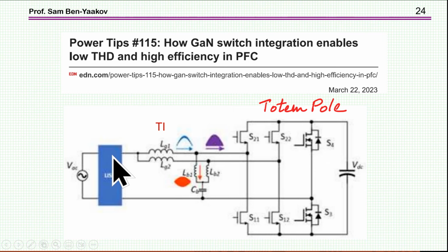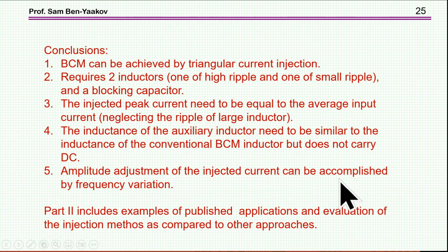So in this case, you again don't need rectification, because you might say that this arrangement is like diodes, except that the voltage drop, of course, is lower because these are transistors, but this actually helps to always provide a positive signal to the output. So these are two approaches and two designs that have been published that I'm going to discuss in more detail in part 2.